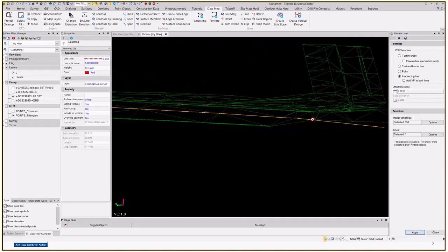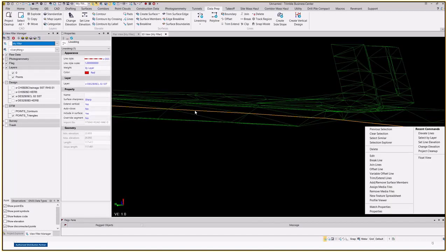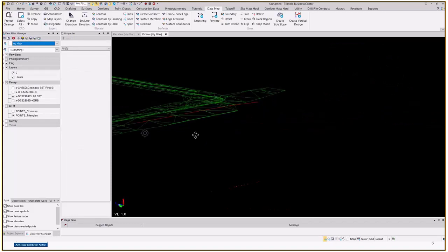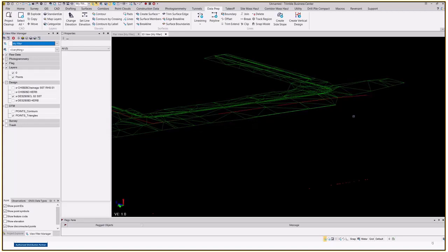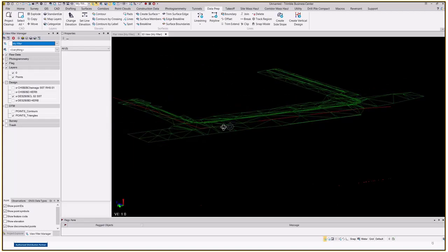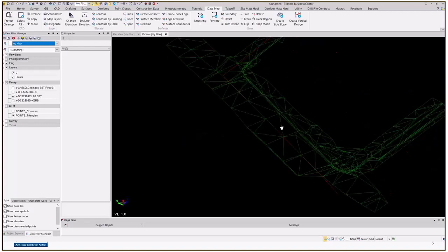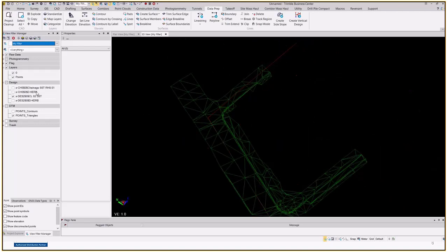Now obviously, as the DTM falls short, we might want to do something with this line towards this end of it, whether we want to project that grade on, assess the grade along the centerline, or go back to the actual drawings and see what it's meant to be at the intersection down here. So that's the quick and easy way to elevate some information. You can then go through and clean up more of your data.